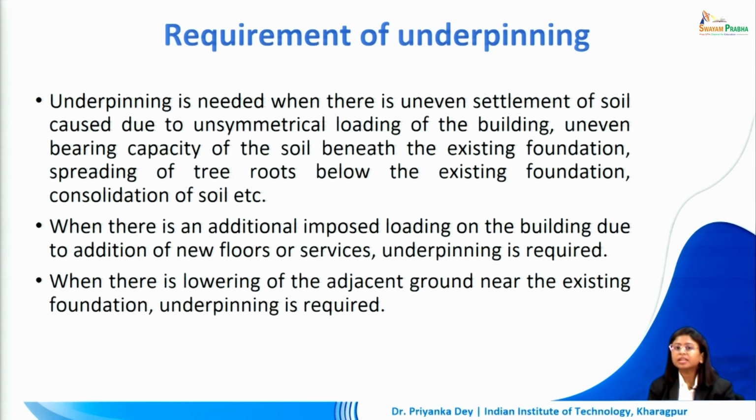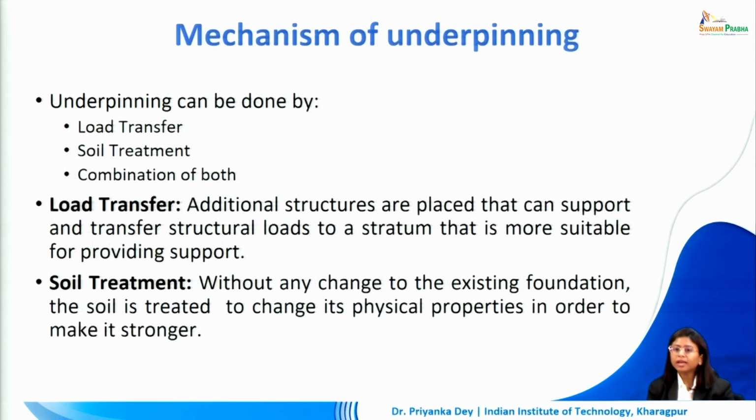When there is an additional imposed loading on the building due to the addition of new floors or services also, we can go for this. And when there is a lowering of the adjacent ground near the existing foundation, underpinning is required. So we now understand why we have to go for underpinning. So now let's see how we can actually go about it and what is the process involved in the same.